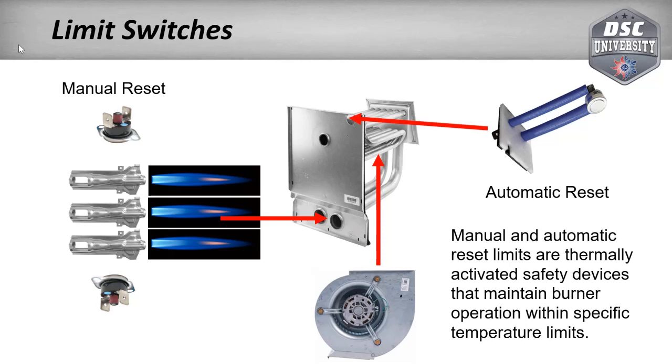And what usually it'll do, if it doesn't trip the limit, it'll usually melt wires and cause the furnace to shut off. Yeah. Back in the day, a lot of times when the flame shot back, they said the heat exchanger was cracked. Yeah, and that's what. So if we had a cracked heat exchanger, what would happen is, you walk around here.